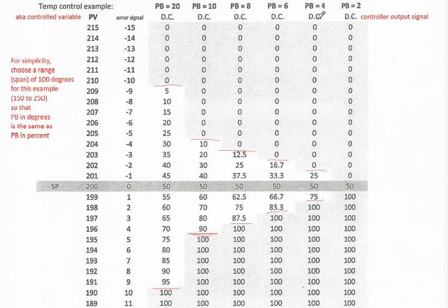Again, now let's compare proportional band and gain. Proportional band has been reduced to 4. Let's take the original proportional band of 20. So we are now sitting at 1/5 of where we were for proportional band. So if you reduce the proportional band to 1/5 of what it was, you can guess what gain should be. Gain should be 5 times what it was, right? To go down to 1/5 for proportional band should make gain go up 5 times.